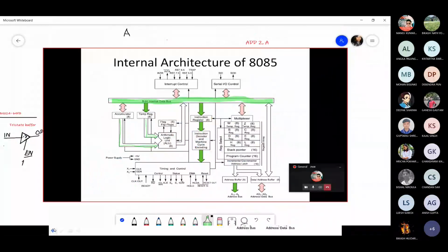So this bus that I have just highlighted and shown in the figure is not the system bus. It is the internal bus that is implemented inside the silicon wafer of the 8085, inside the 8085 chip. Please note, all these parallel lines inside the chip are implemented as wires by high doping, or sometimes, and nowadays, they even deposit layers of aluminum inside the silicon wafer